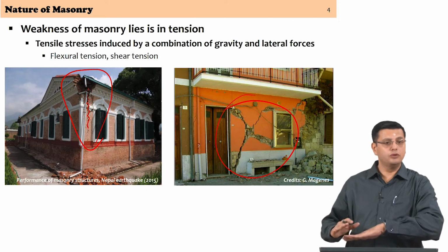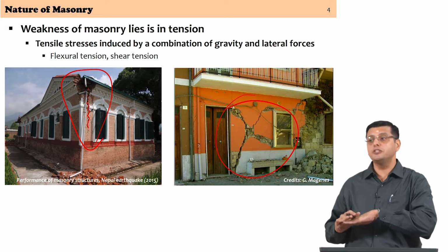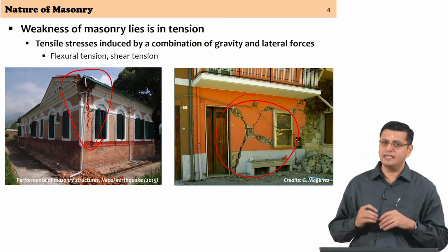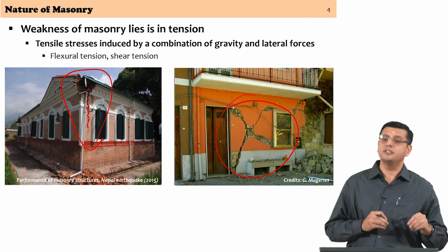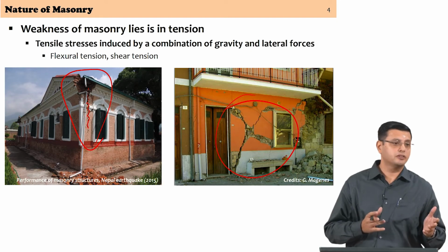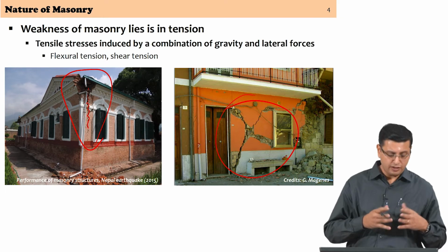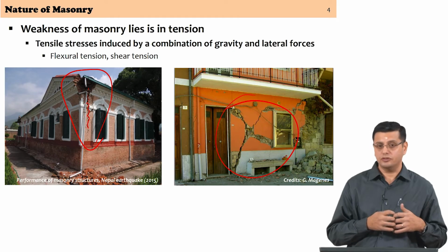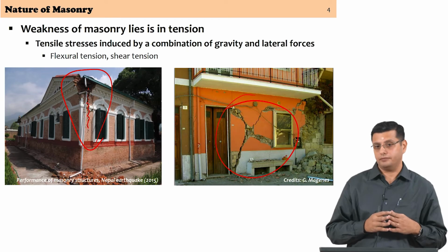This limitation, understood at the component level, a single wall, is the basis with which many of our historical structures have been constructed, and we will examine that in a few minutes. Similarly, in regions of significant earthquake activity or heavy wind forces, you have ties that basically hold all the masonry walls together. So, you need something else to keep the structure together.